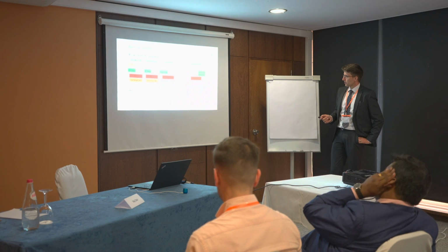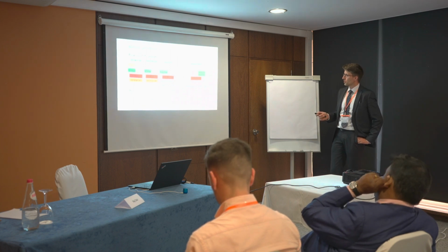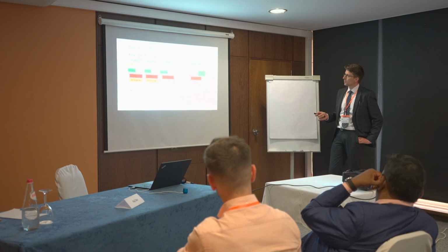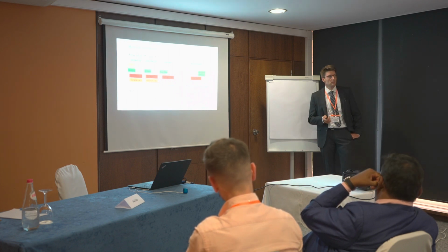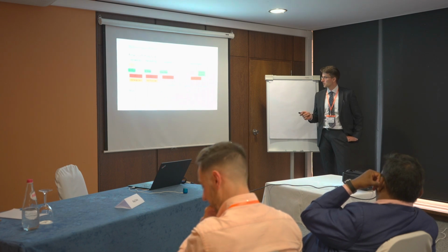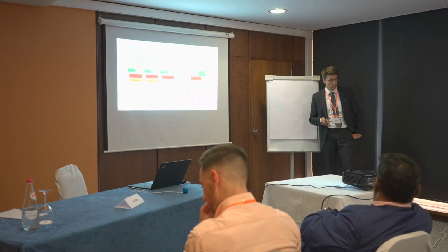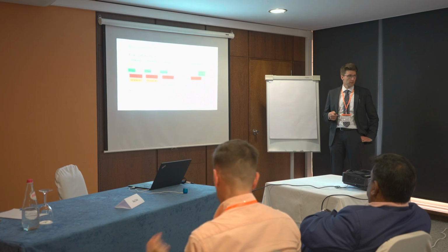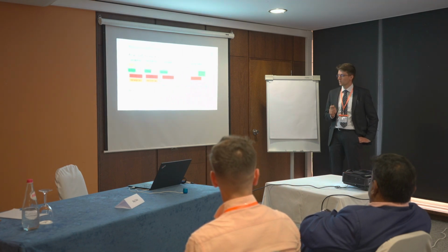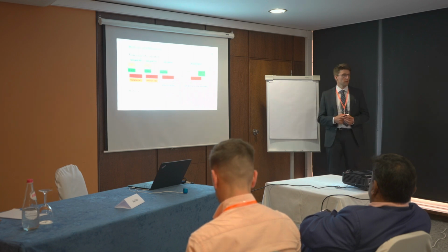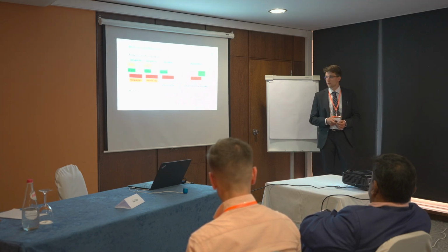So with the proposed method, we just measure the voltages at the bars, the incident pulse, the reflected pulse, and the transmitted pulse, and we measure the displacements at the two interfaces, and from this measurement we directly calculate K1 and K2, the two calibration factors, and then we can perform a test, or as you will see, we can also use an actual test to calibrate the test. For the material, we use high strength quenched and tempered steel with the characteristics shown here.